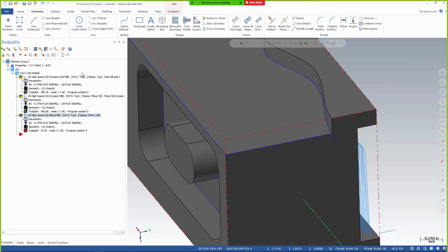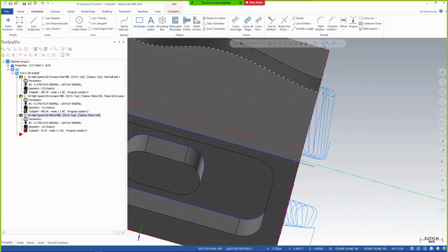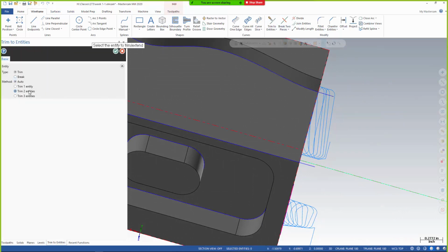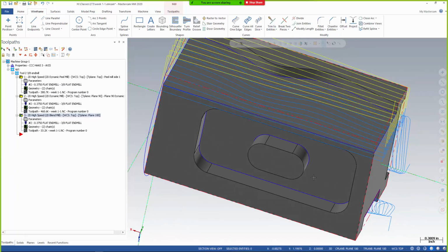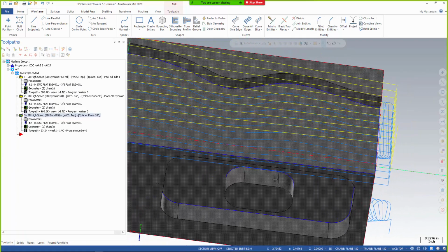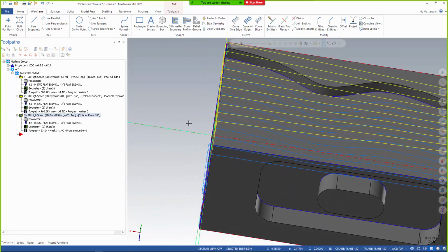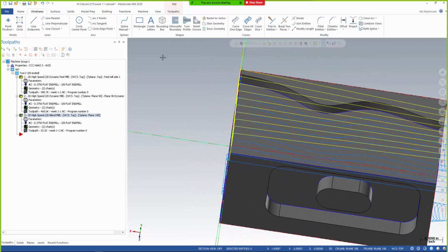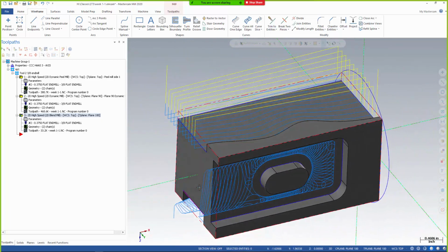So I'm just going to go ahead, and those two are actually, let's trim them. So I'm just going to go to wireframe, trim, that to there, and that to there. So we should have the same exact result. So there, we have the extra lead-in. It's not leading out any because we really don't have to. Bear in mind, we're going to have fixturing or the subspindle, or it could be fourth axis on this end. It just depends on what's going on.